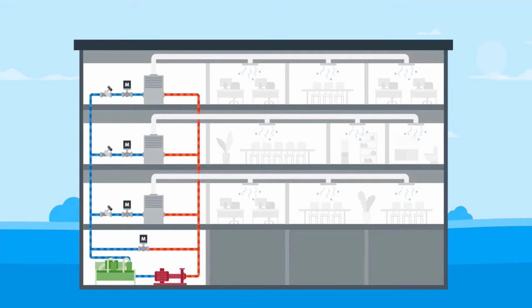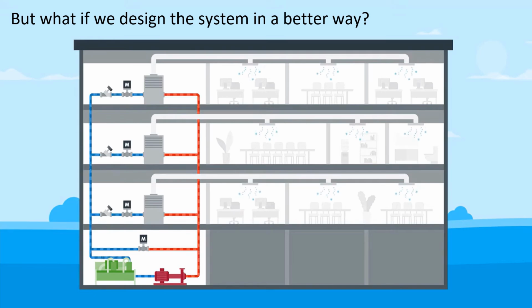For a large plant, small plant room and building, it is good to go with the primary variable and the secondary variable system. But for a large campus or large building, a distributed pumping system is advisable in terms of configuration. So it matters what kind of system we design for better building control. Let's evaluate the difference between the distributed pumping system and a primary secondary variable system for any commercial building cooling application and others.